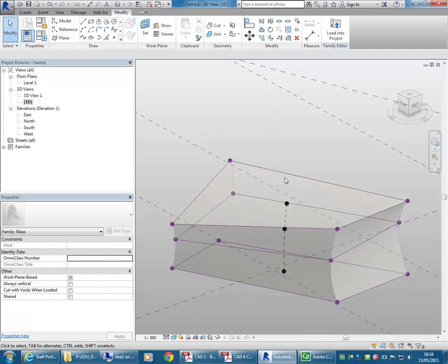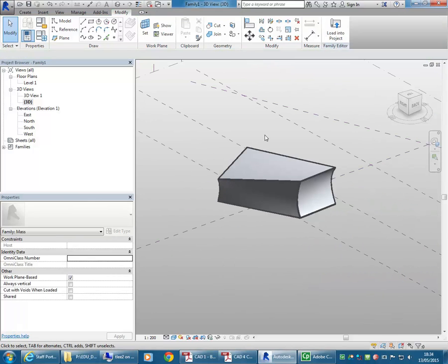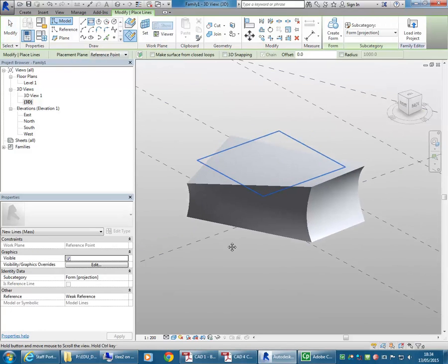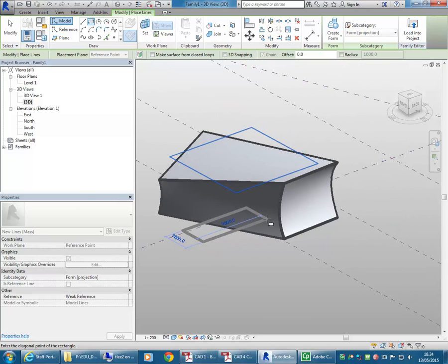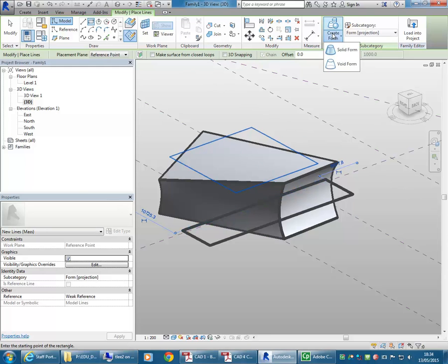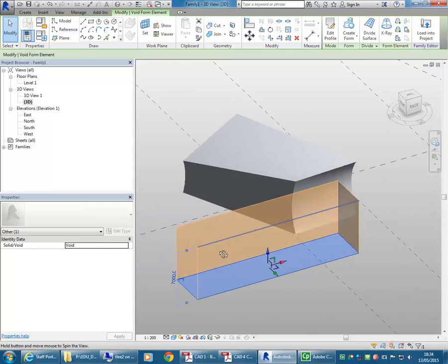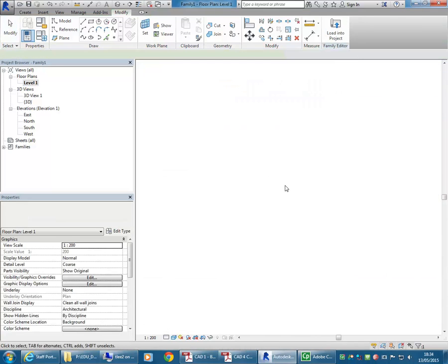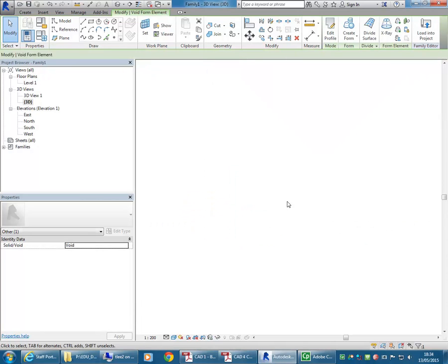So that again, if I go and select any of those forms, I can turn X-ray off, and then can keep making further forms. So I might want an opening through this, and so using create form, but this time going to the sub option there and choosing void form. Oh, I thought that was intersecting. I'll just check that above. Okay, so I'll just drag that over,